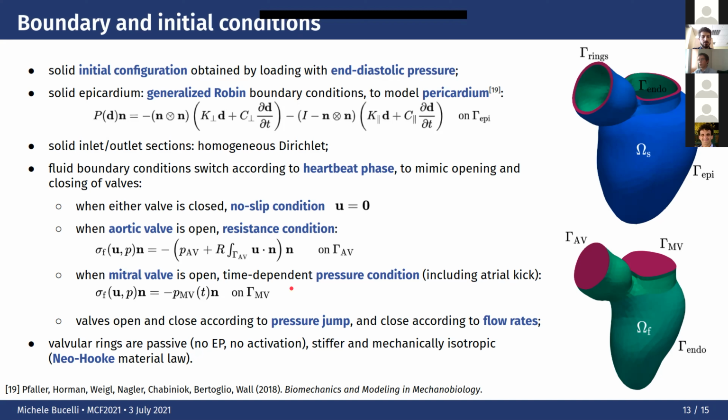One important point here is that opening and closing of valves in this simulation does not happen at prescribed times, but happens according to simulation results. So valves open when the pressure jump across them becomes positive, and close when backflow occurs through the respective section.